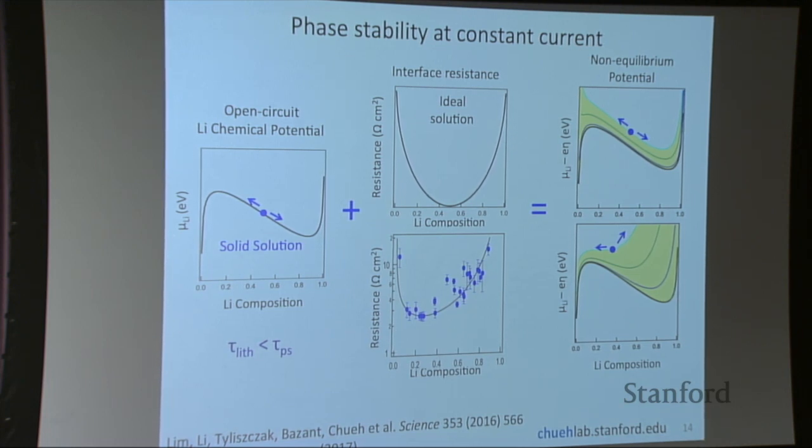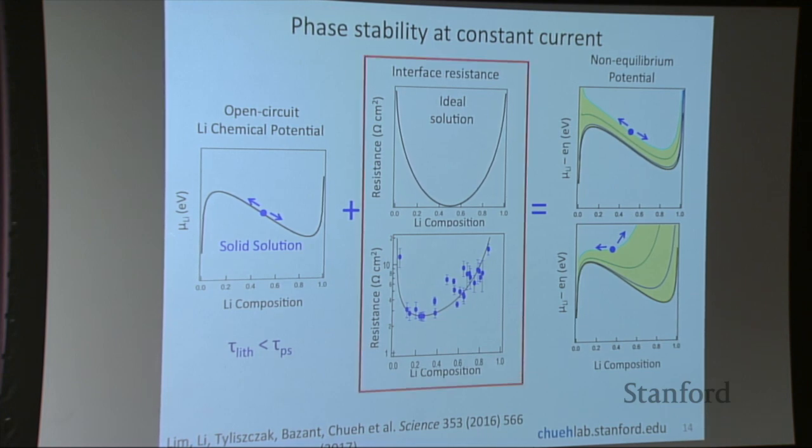And the reason we don't want phase separation is we don't want those boundaries, which have enormous stress associated with them, to fracture the particles. So we actually now have a very good explanation why these particles cycle so well despite undergoing this huge multiple thousand PSI boundaries between the two phases.